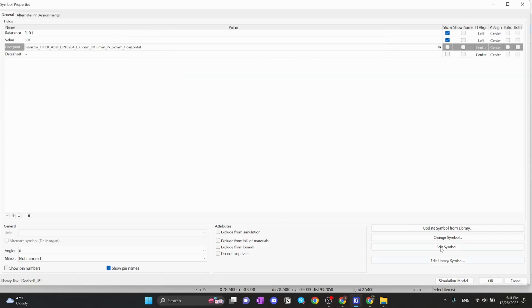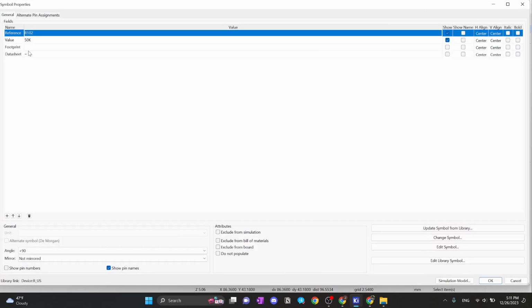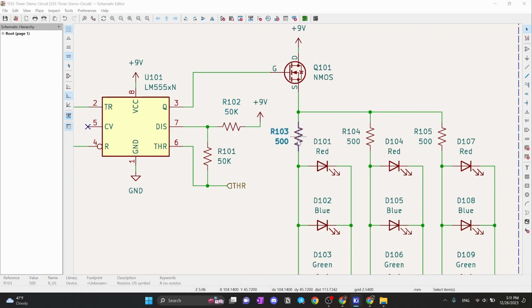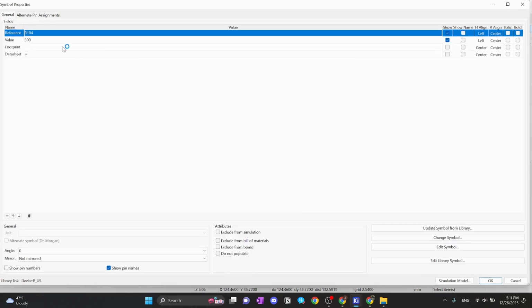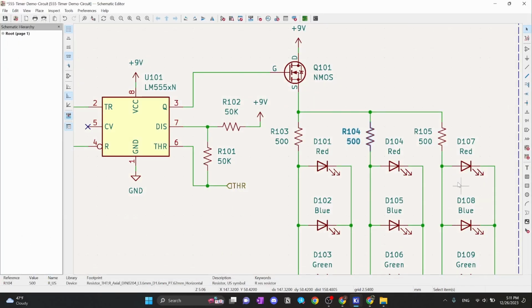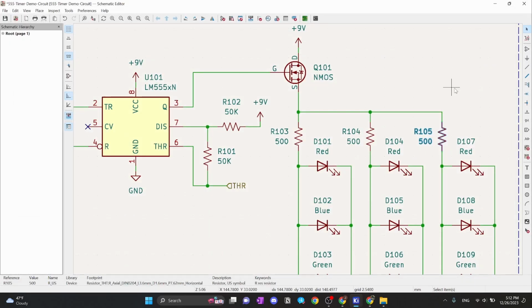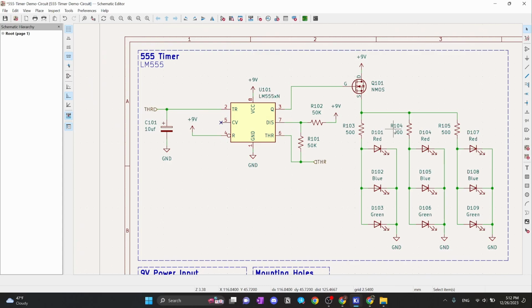That's what we're going to use. And because we have 5 resistors, let's copy this, OK, and paste that for every single one of those resistors. Again, you can either double click into them and paste that, or you can single click and hit E. All right, so that takes care of all of our resistors and capacitors.